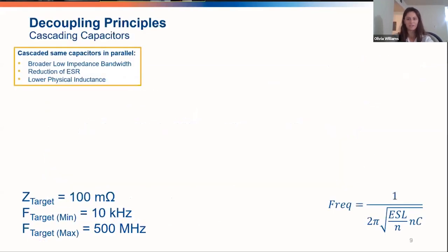Now let's look at an example where we'll try to work our system down to the calculated impedance. Back in the early days of PDN design, which I wasn't around for, it was the thing to just put a number of 0.1 microfarad capacitors close to the active device leads.